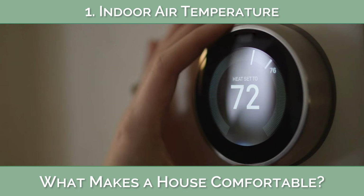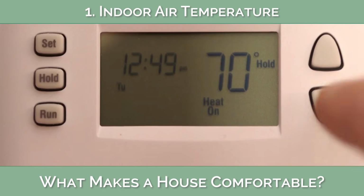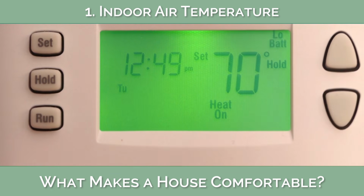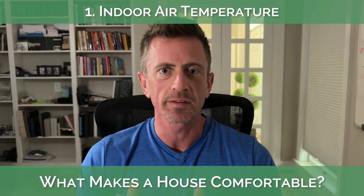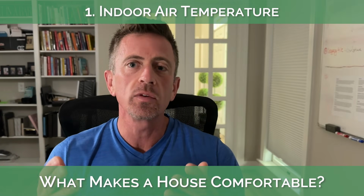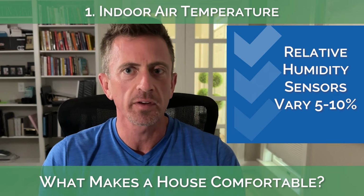This is the temperature that you set your thermostat to that makes you feel comfortable at home. The thing is though, every thermostat is different and each one reads temperature and relative humidity a little bit differently. So one thermostat right next to another one in the same room could be off by 2 to 5 degrees. They're even worse when reading relative humidity, and they can be off by 5 to 10% or more.